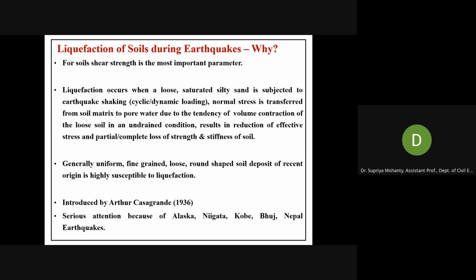For soil, as you know, shear strength is the most important parameter. The soil fails in shear, so we need to consider the shear strength of the soil while designing the structure. Liquefaction particularly occurs when loose saturated silty sand or sandy soil is subjected to earthquake loading, maybe cyclic or dynamic load.